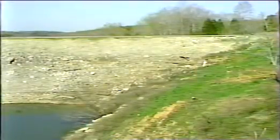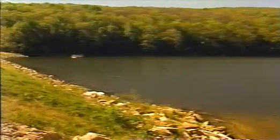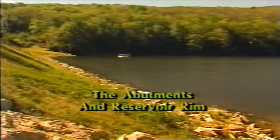Deficiencies that jeopardize the safety of a dam are not always found on the dam itself. Problems can also occur on the abutments, around the reservoir rim, and in the area downstream from the toe of the dam. Many of the same deficiencies found on an embankment dam may also be found on the abutments and reservoir rim. On the downstream side of the abutments, look for signs of seepage, such as wet spots and lush vegetation. Stains on rock surfaces may also indicate seepage or that solutioning of the rock is occurring. Note the location of any seepage areas.